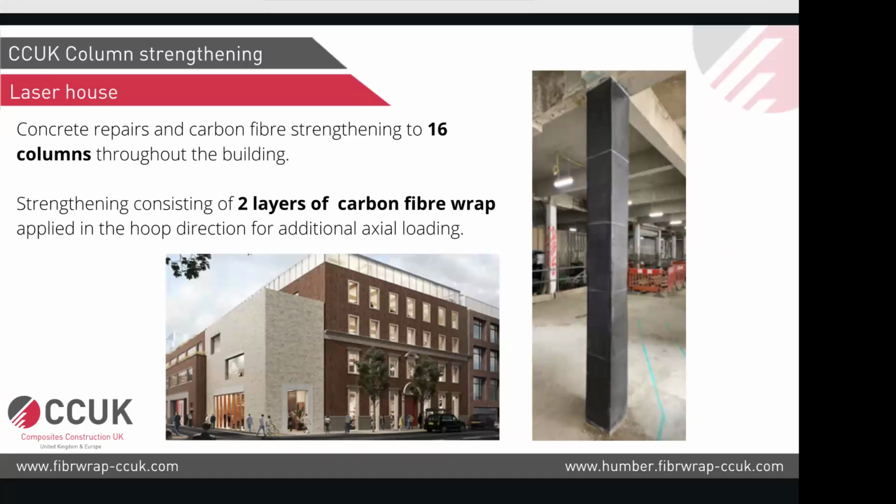Now the solution the engineer proposed there was to take this encasement off, weld another plate of steel onto the flanges of the column and recast this encasement. And for that reason, they needed around 80 of the columns strengthened. So if you go with the same method, it will be a very destructive way to strengthen.